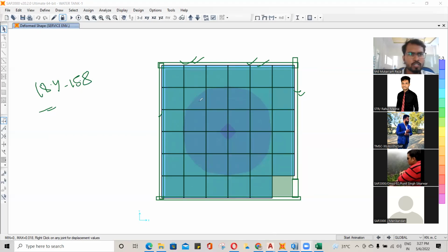That is called axial shortening. This is what I was also thinking, ma'am. I was thinking that with the current, if we elevated, then best. Understood. Where you have to check. Yes, sir. So if you are checking the deflection here, you check the deflection with the support also. Correct, no? You do the minus sign, subtract this value from here to here. You get the exact deflection.